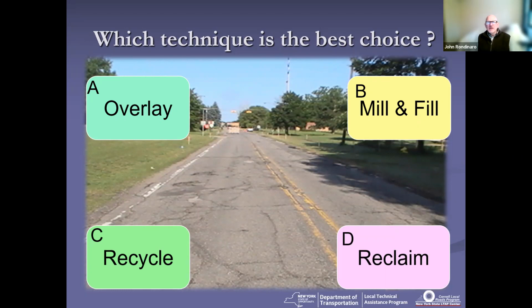Okay, gotcha. Well, I'm going to agree with the B and Cs. What do you think, David? I want to do some coring or test pits to know for sure. Exactly. What's underneath, because it's also possible it needs reclamation, and I'd certainly look at the drainage too. Yep, absolutely. And so to David's point, if with that further evaluation, taking a good look at your cores and maybe a test pit, if you've got foundation problems, reclamation is probably going to be the answer.